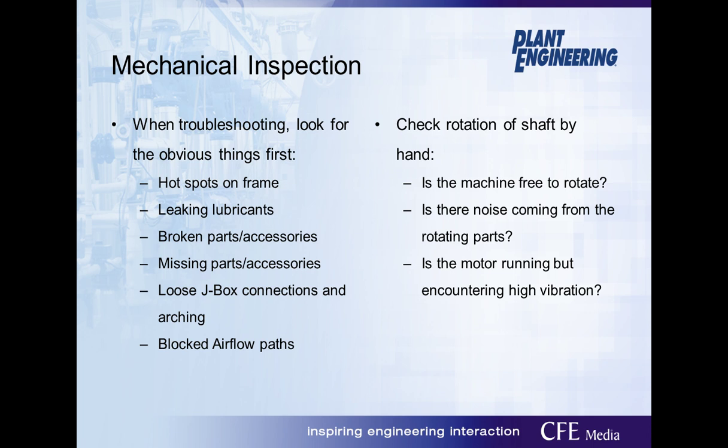As we touched on earlier about motor enclosures, it is always good practice to look for blocked airflow paths. For example, on a TEFC motor, totally enclosed fan cooled, there are a lot of applications that can cause the fan cover vents to get blocked from the materials in the environment. For example, damp paper, damp sawdust particles, rock dust, concrete, or even metal slag. There are so many different contaminants that can produce cooling problems, but sometimes it is just the basic human errors of leaving a box too close to a motor or adding components to a motor to help with contamination buildup, but not allowing enough room for air to flow properly.